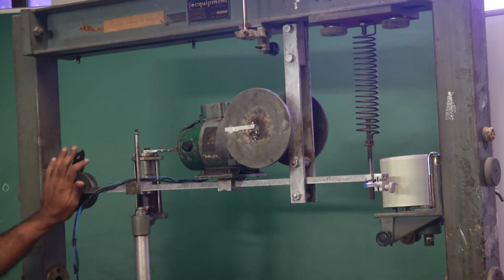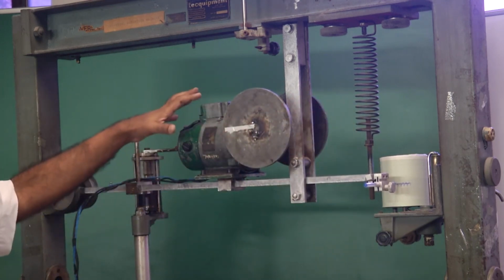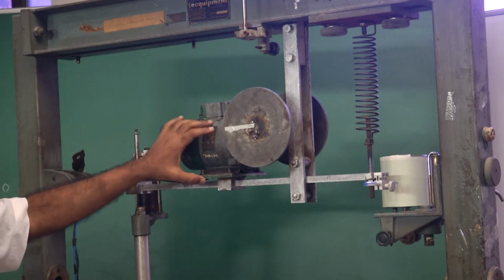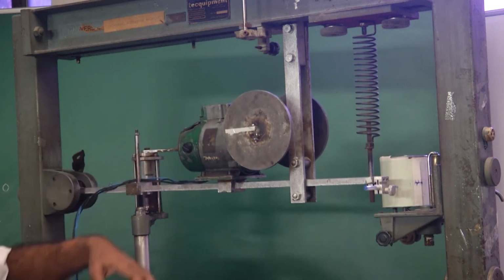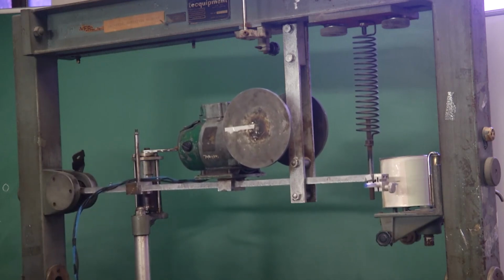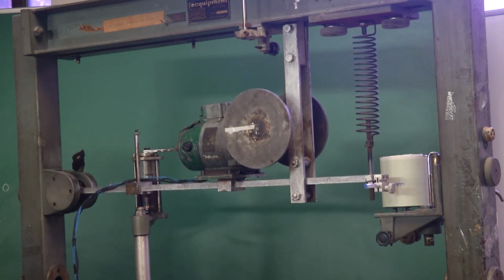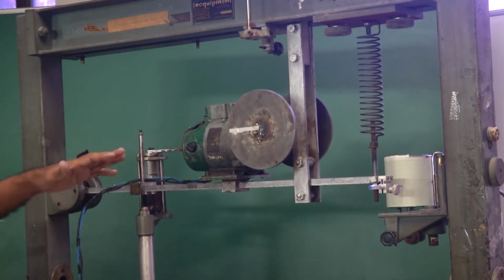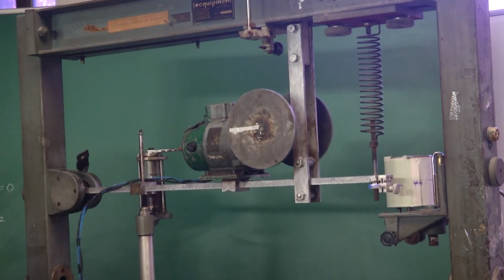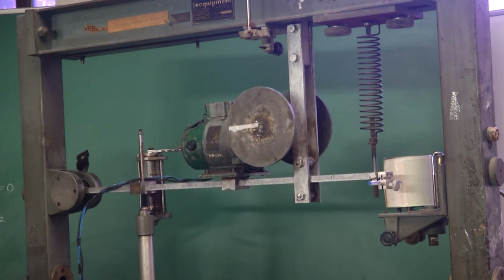So, this is one source, structural damping is the other one, and based on the shape and size of this motor, you may notice that as it keeps swinging back and forth, you may also have a very little aerodynamic damping as well. So, there are various sources of damping, but in this particular case, all these mechanisms provide very little damping, and that is the reason why you see that the amplitudes are not decaying so fast as compared to the other case, which I will show you shortly.